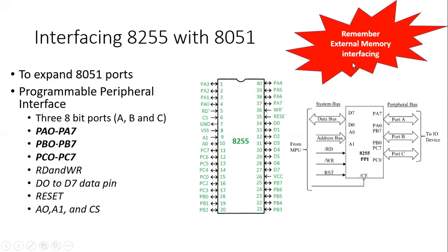External memory interfacing we have studied with the 8051 microcontroller, where we use the ports for carrying the address and data, and we also had latches in between the microcontroller and the memories, and there are also read and write pins and chip select pins. So the same concept is going to be used here for interfacing 8255 with 8051. Hope this clears most of your doubts about how to use 8255. Just remember how to interface the external memory. The same concept is going to be followed here.